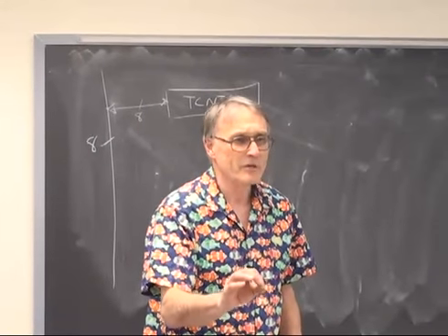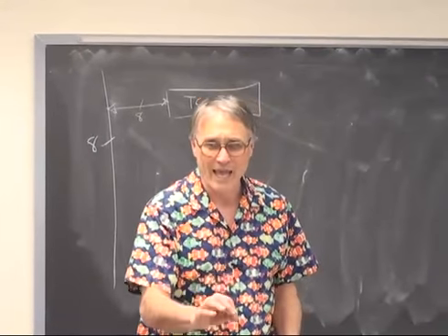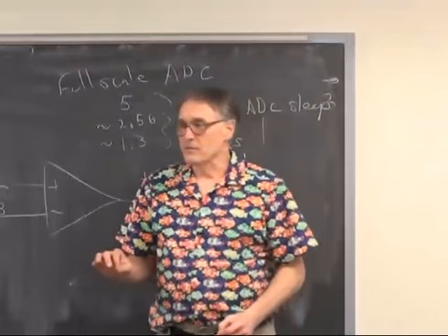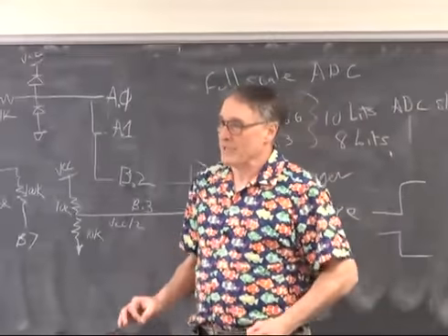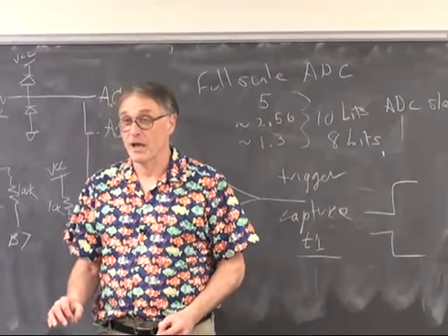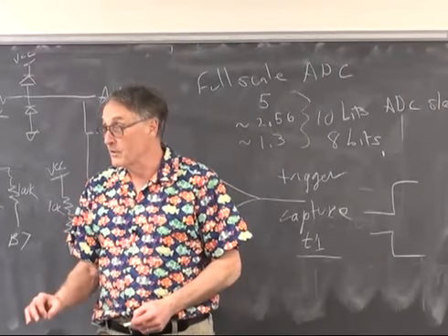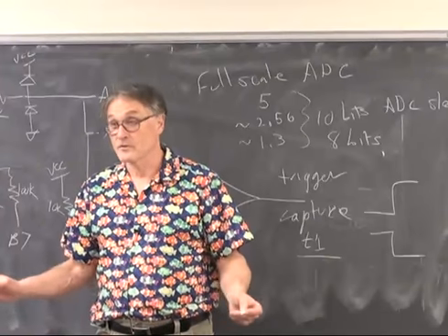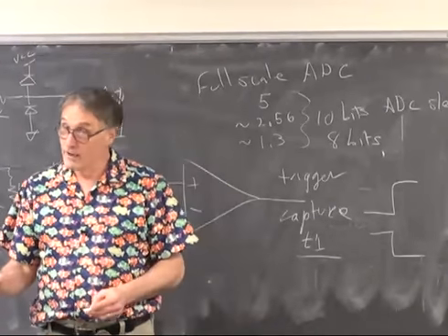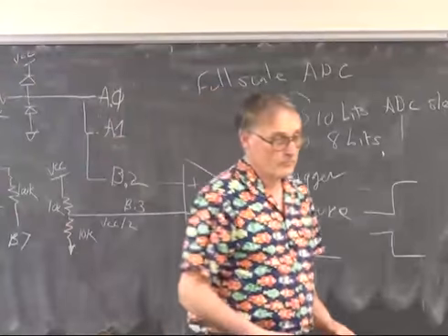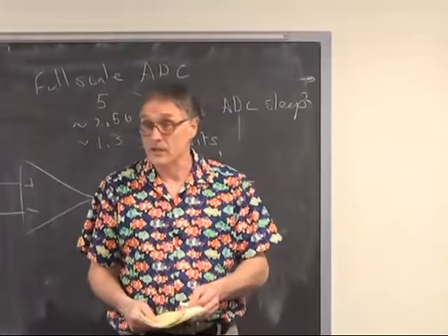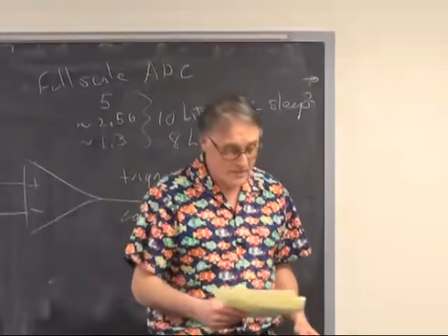If you never read it, you never read another value again out of that register. If you expect to read a 16-bit value, you must read the high value. If you read the high value first, then the low value, the timer is frozen forever. You have to read the low value, then the high value. If you just use the 16-bit reads that are built into C, you don't have to worry, because it does the right thing.